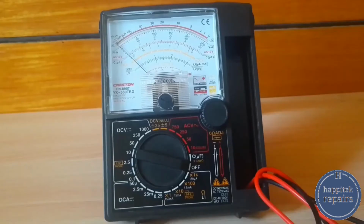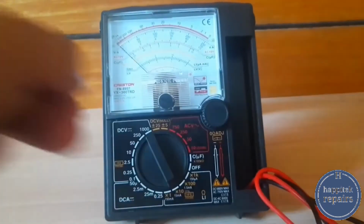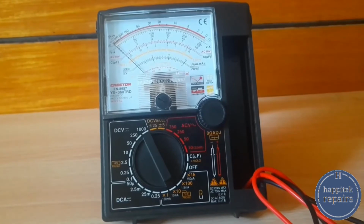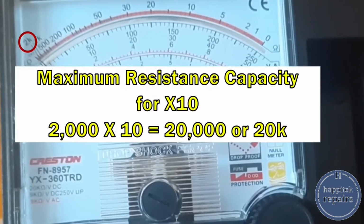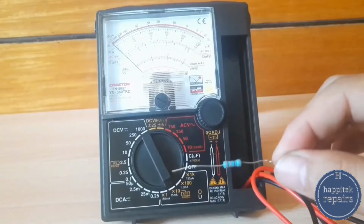If we set the Ohmmeter to X10, the resistance is equivalent to the reading times 10. The setting also tells the maximum it can measure. For example, in X10, the maximum resistance it can measure is 20k ohms. This is because the number we have on the Ohmmeter is 2k, and 2k times 10 is 20k.